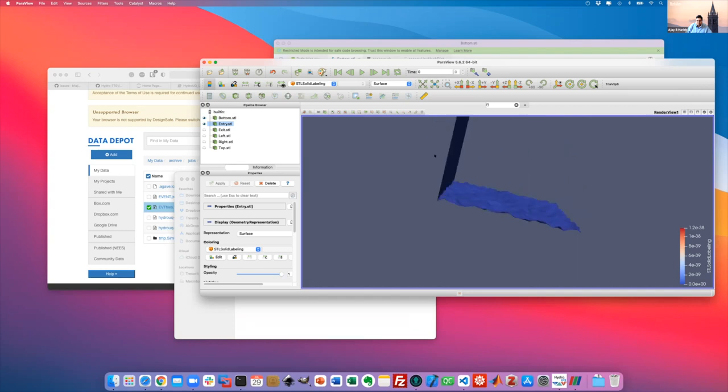The only caveat is that all the STL files together should still form a watertight geometry, and that is one problem. So when you write an STL file, you need to be careful that the files you're giving form a watertight geometry. Often with STL files there can be gaps and things when this should not happen, and this needs to be taken care of.